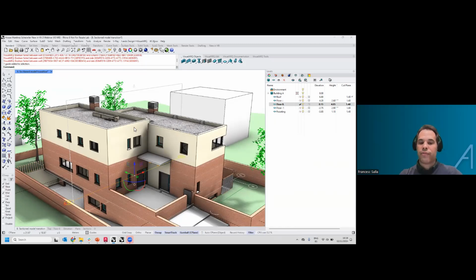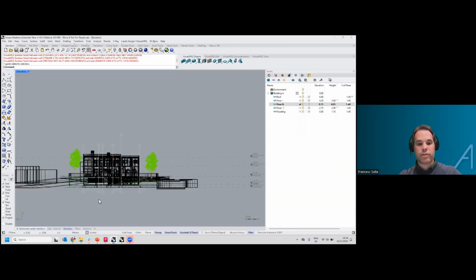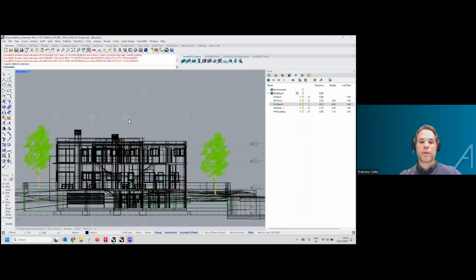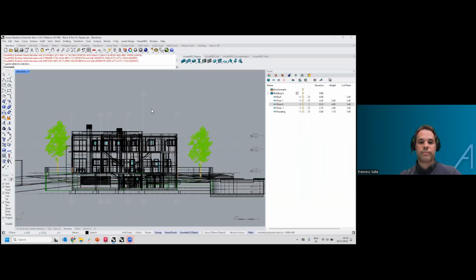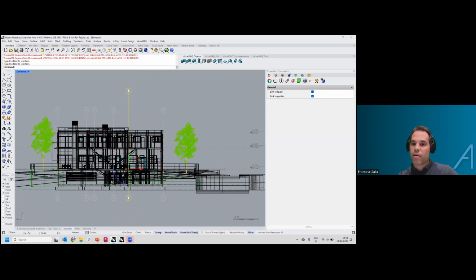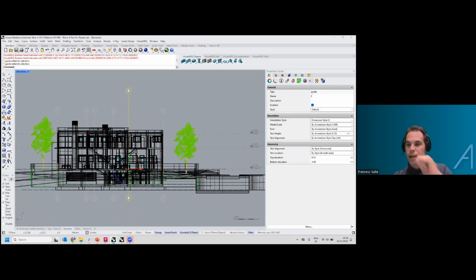And when we see a guide perpendicularly from the elevation views, we see them also with this line and a label at the top. So for example, this one has a higher range. Later on, we can adjust the position of this label by the extension arrow, or we can go to the properties of this label and define here the top elevation to any other value. By default, they are placed 4 meters above the elevation of the last level as the top elevation, and 1 meter below the elevation of the inferior level.